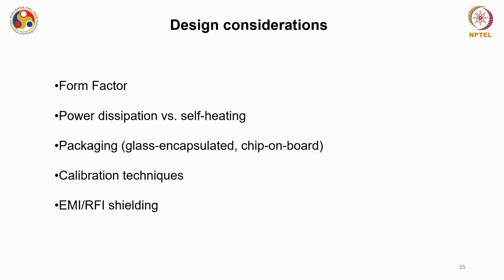As I have mentioned earlier, glass encapsulated NTCs are very rugged in nature, but your requirement may be chip on board. So the packaging you have to consider initially while designing these sensors. Then what calibration technique you are going to use for this NTC thermistor has to be understood while designing this sensor, and of course EMI RFI shielding is very crucial for this kind of device.